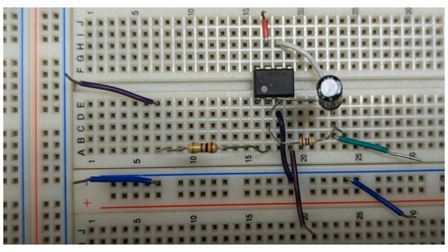First, let's look at the circuit setup. We use an op-amp with a resistor and capacitor to create a first-order low-pass filter. The cutoff frequency is calculated as 1 over 2 pi times R times C.